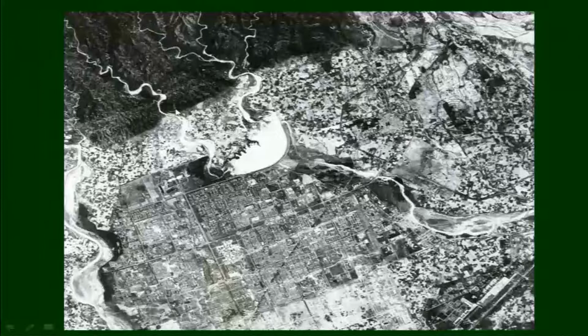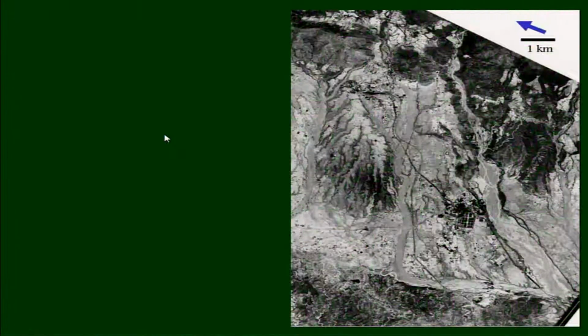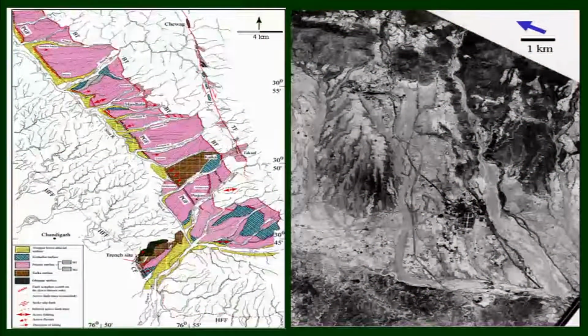And the fault line which marks the boundary between the Shivalik hills and the Indo-Gangetic plain is termed the Himalayan frontal thrust. So another signature. What we usually do is try to identify the active features or tectonic geomorphology. Based on the tectonic geomorphological studies, we try to identify the active features which are tectonically formed, and mark and